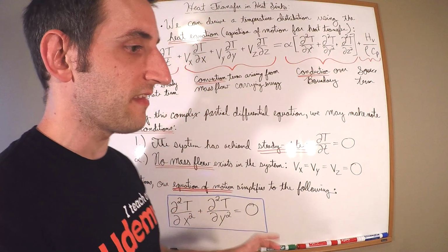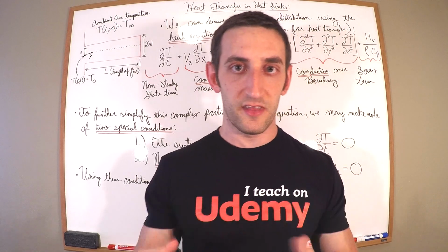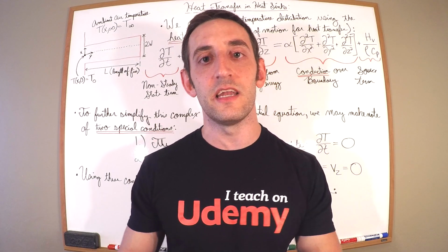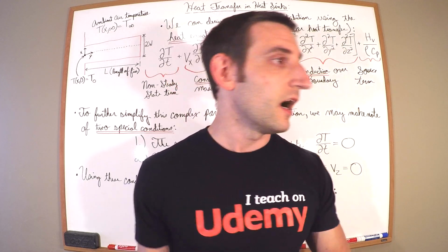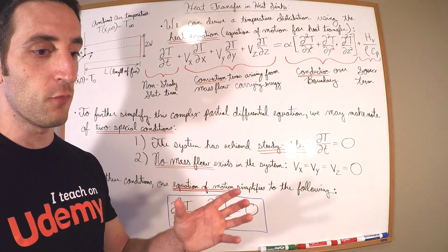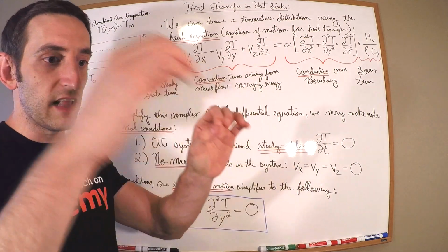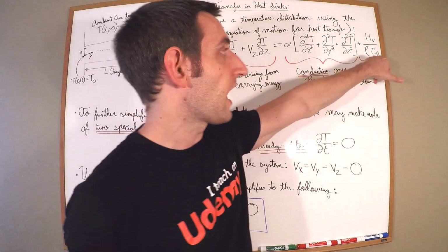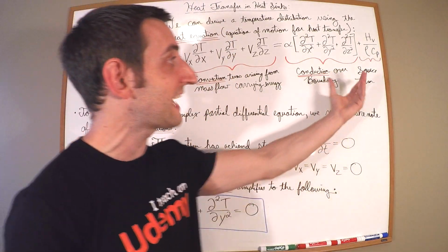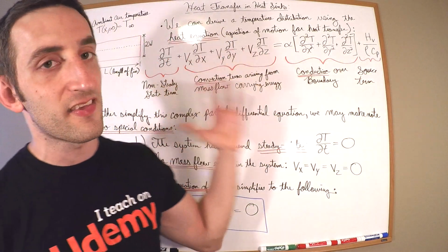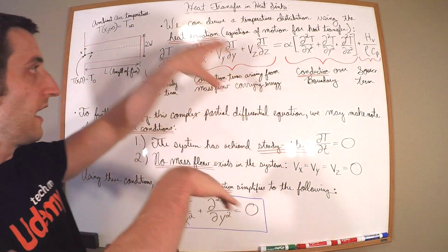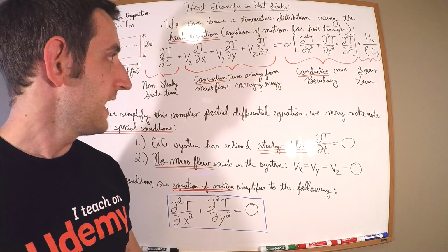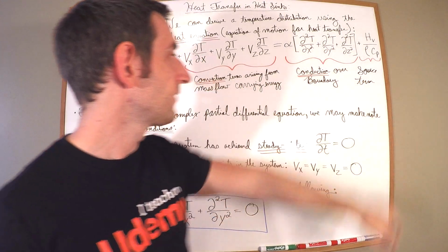What this accounts for is if energy is generated within the material. How can that happen? That can happen with electricity in wires, for example. If you hold a wire and the electricity flows through it, that electricity generates heat. Okay? That would be this guy. It's being produced within the material, so you need to account for that. In essence, this is just an energy balance. Energy flow on the left equals energy flow on the right. Okay? So that's the source term.